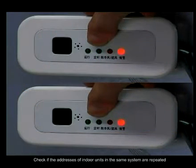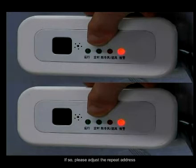Check if the addresses of the indoor units in the same system are repeated. If so, please adjust the repeated address.